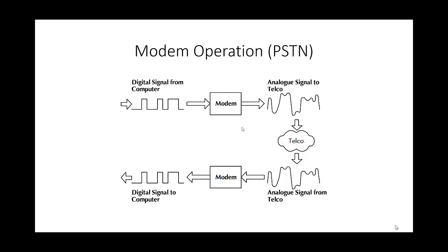The modems used for PSTN connections are asynchronous, i.e. they do not exchange a timing signal with a digital data source, usually a computer or a router. The modem needs to detect each bit sent by the computer. To do this, it must sample the digital data from the computer at exactly the same rate at which the computer generates it. The lack of a common clock at either end means that the modem and computer could become out of sync with each other when transferring long streams of data, resulting in bits being missed or counted twice.